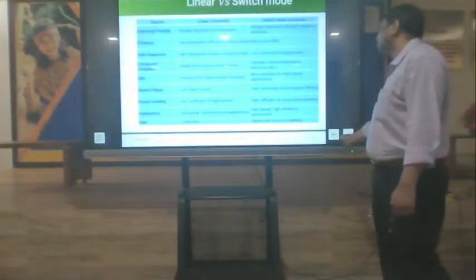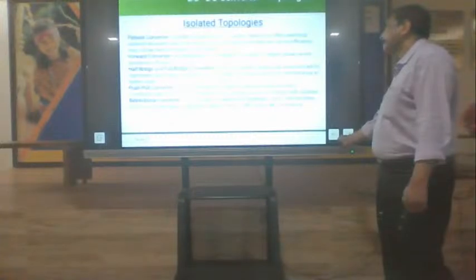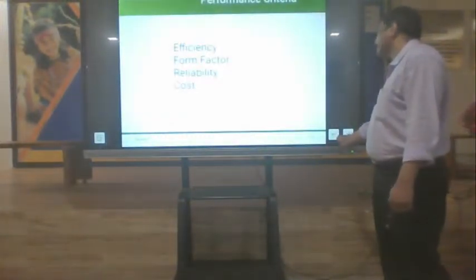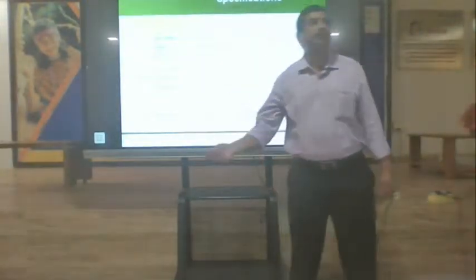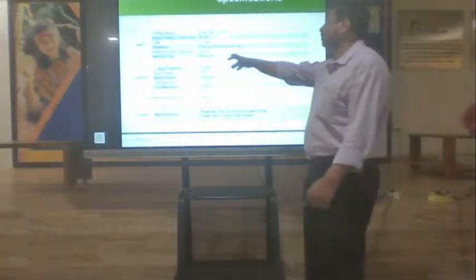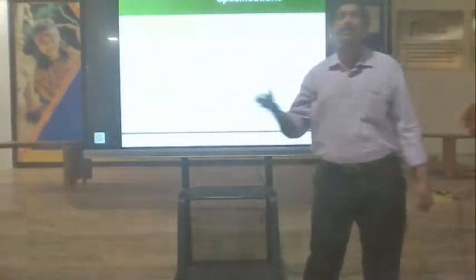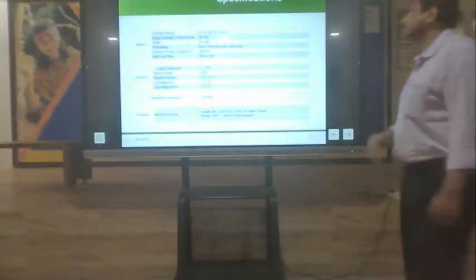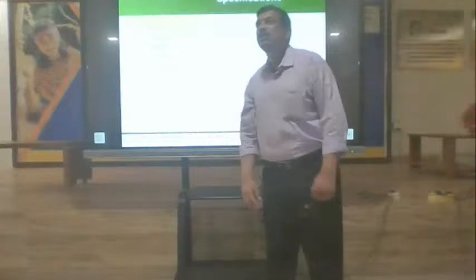That is generally very low, about 500 milliwatts, a few milliamps. Nowadays, the industry benchmark is that instead of internal circuits consuming milliamps, the internal consumption is around picoamps. So instead of milliwatts, it is microwatts.